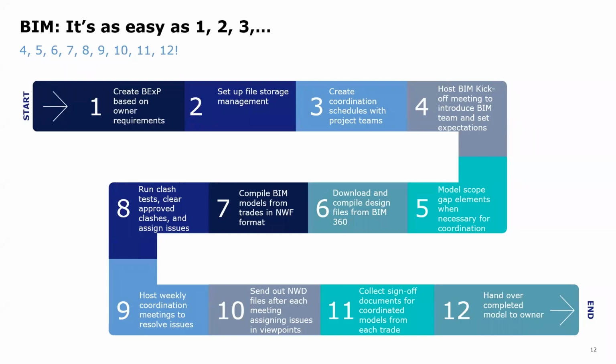And do you mostly model with a sub's BIM team or with an engineer? So the engineers are the designers, and they'll hand their models over to the subs on the contracts that we're working on right now. Then the subcontractors will populate it to a specified level of development, which is like whether or not they have hangers modeled, or whether they have the exact system or just a placeholder that's the same size. We won't coordinate anything until it's handed over to the subcontractors, and then we'll coordinate it from there.